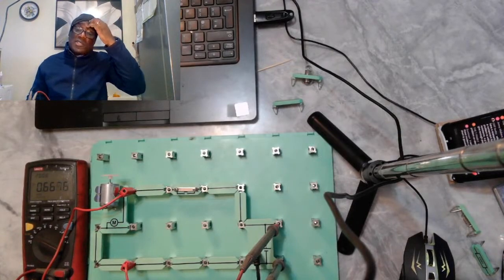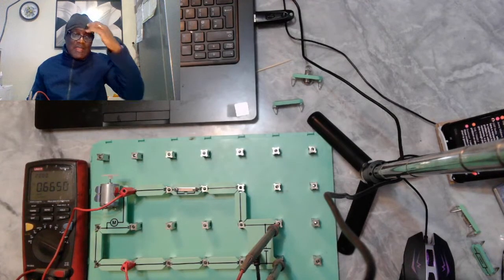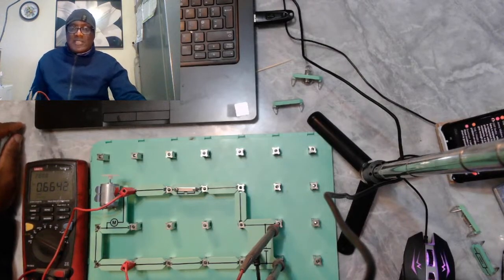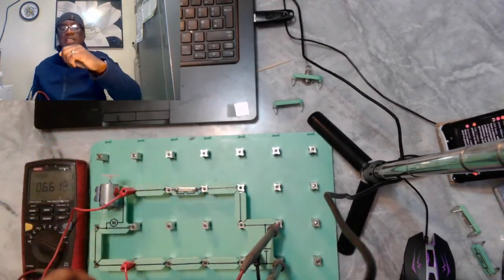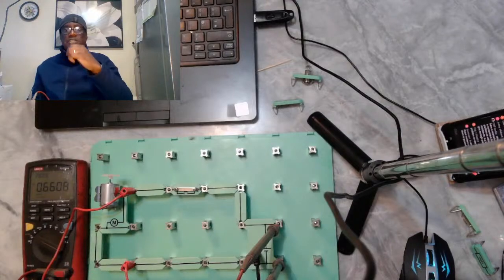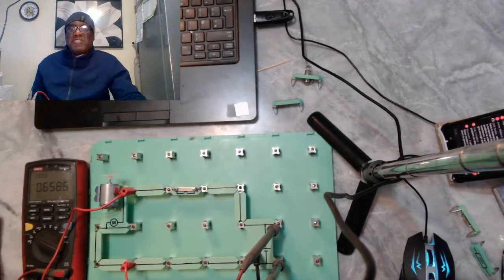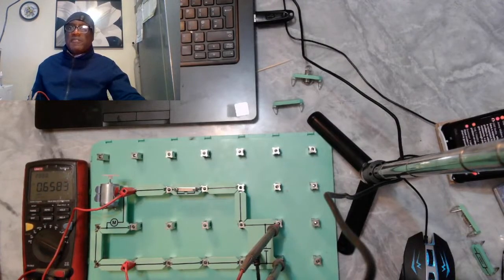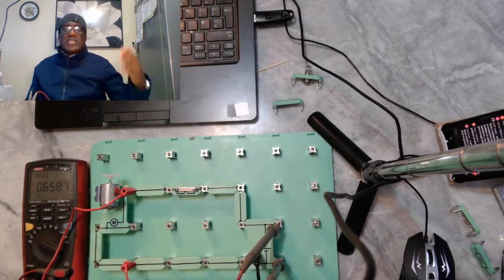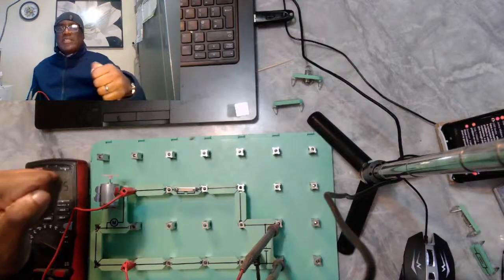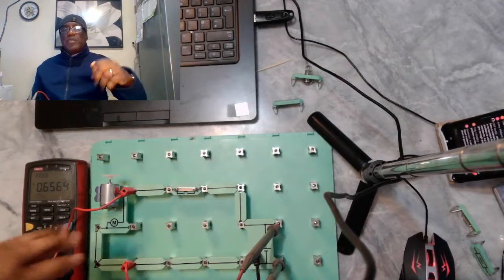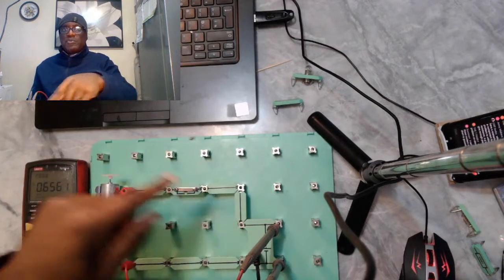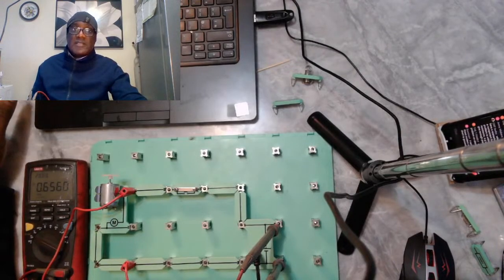The reason why I say don't use a temperature sensor is that a temperature sensor uses 5 volts, but the moment you click it on, that voltage drops to 3 point something. Some of the cars, also 2.3 something or 2.5. So don't use that one. You want a sensor that, when disconnected, will give you 5 volts straight away, and when connected, it will still give you 5 volts. But the temperature sensor by nature drops when you connect it. Why? It has two resistors in series.